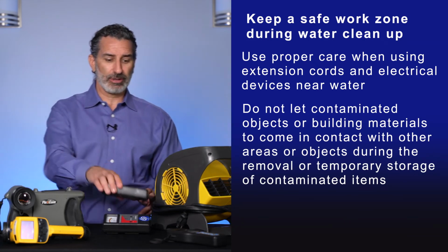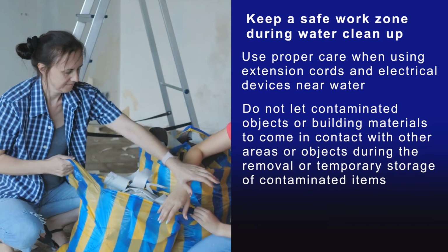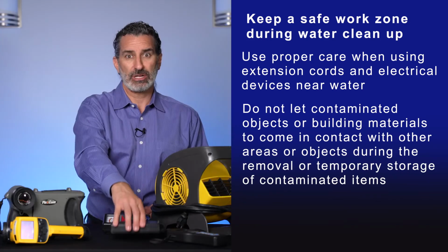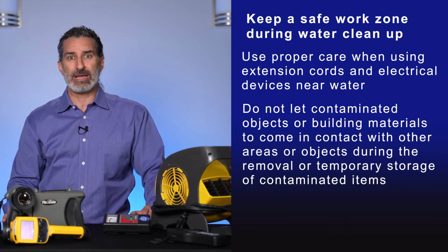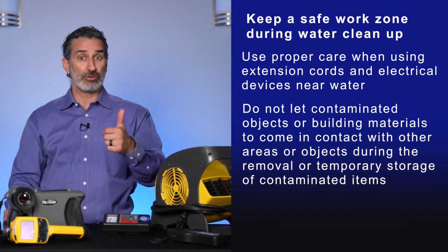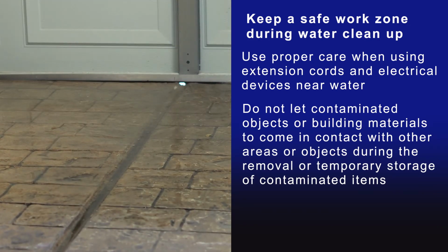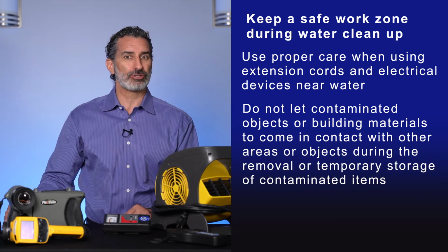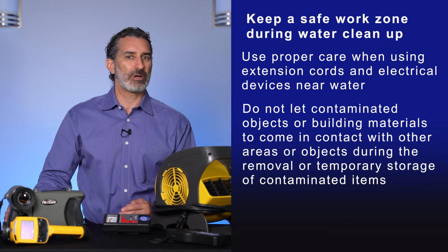Well, if it's category 3 water, you're basically taking a sewage-laden box of papers or a sewage-laden couch and putting it in a room that otherwise would not need to be addressed, but now is part of the loss because you've moved sewage from point A to point B. You've tracked in and out of that facility, possibly contaminating yourself, your vehicle, your tools. So keep in mind that there are hazards that you need to be aware of if you're going to be doing this work in-house.